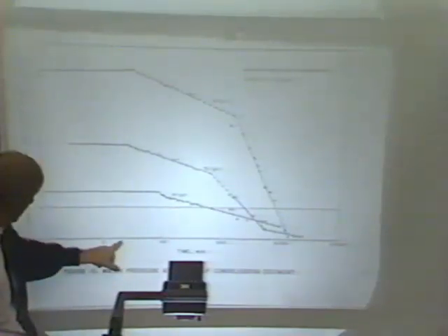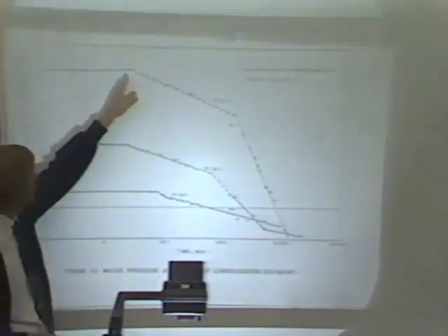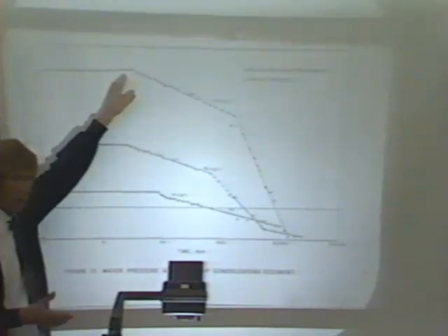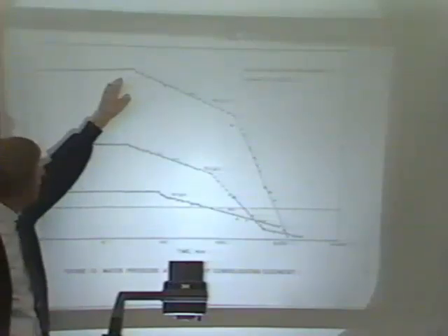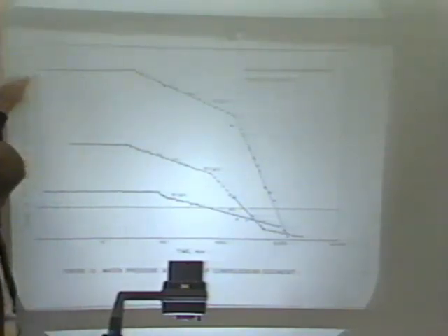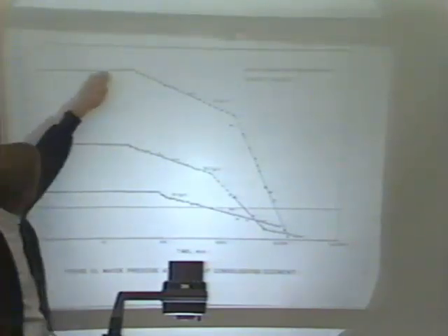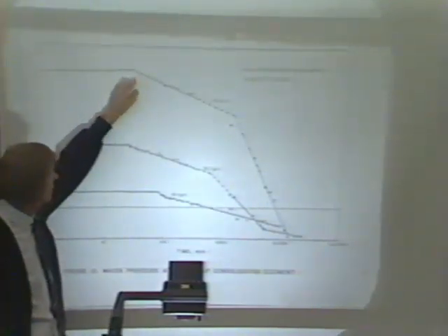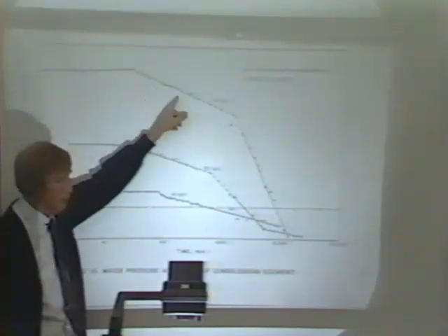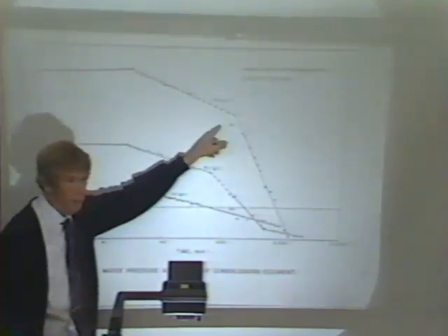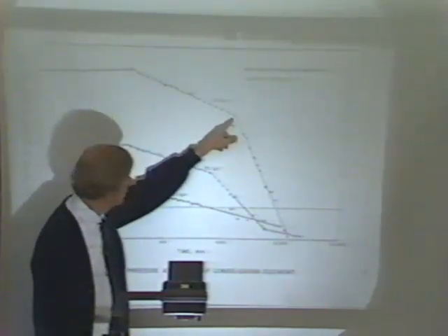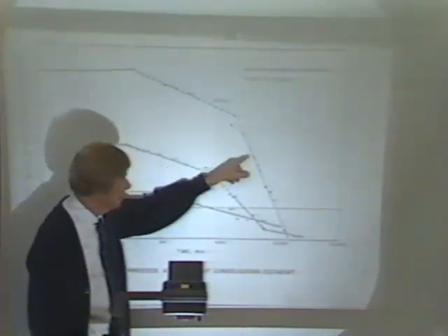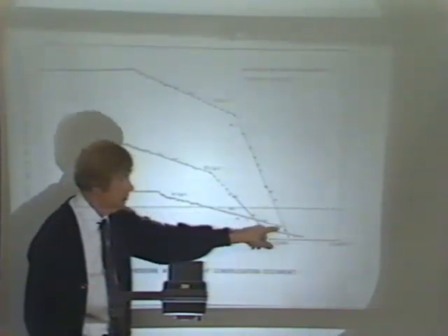difference in elevation. But then as the material settled onto the membrane, you'd expect the pressure to decrease, and it did. But then after it settled on the membrane, it decreased more and more until it decreased below the level of the initial level of the manometer when there was just water in there, indicating that the material had deposited, had settled onto the membrane, and that after it deposited and settled on the membrane, it kept taking up water.